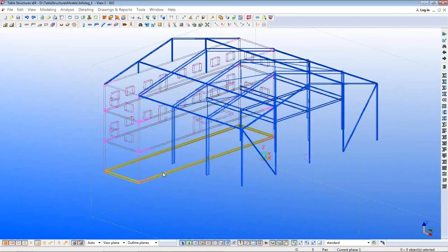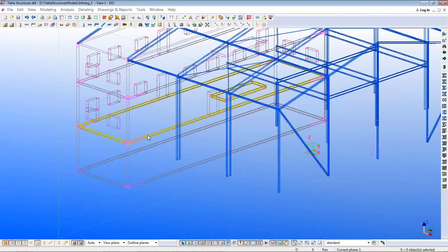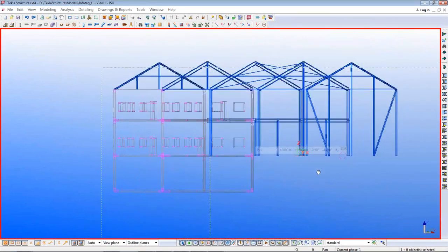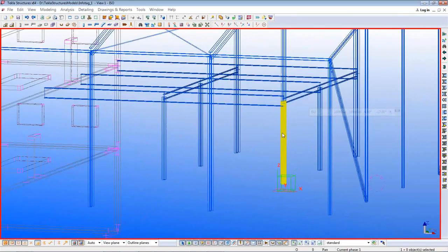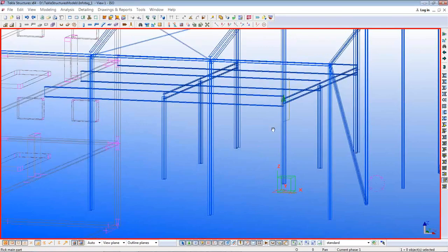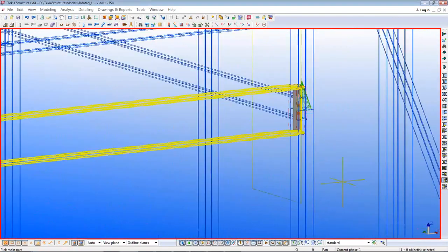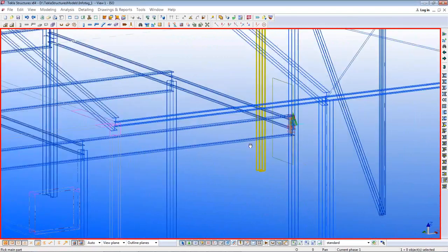You see here also all important information like thickness of the slab or cross-section information are matched, similar to what we do with Revit. The detailing engineer can right away start now to create, for example, some connections. I can choose, for example, a shear plate connection, create a small connection here, which is more or less intelligent.